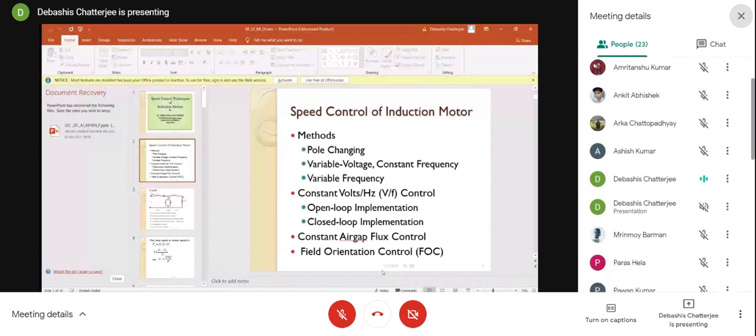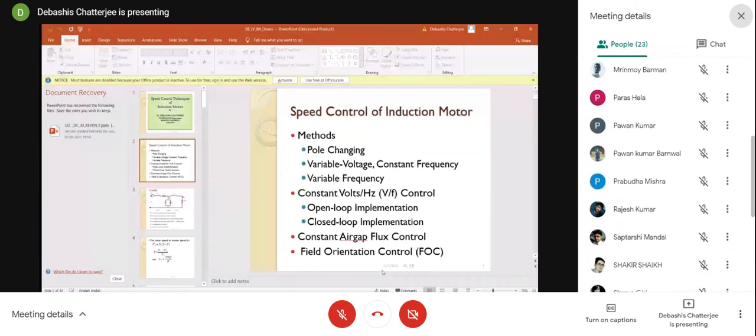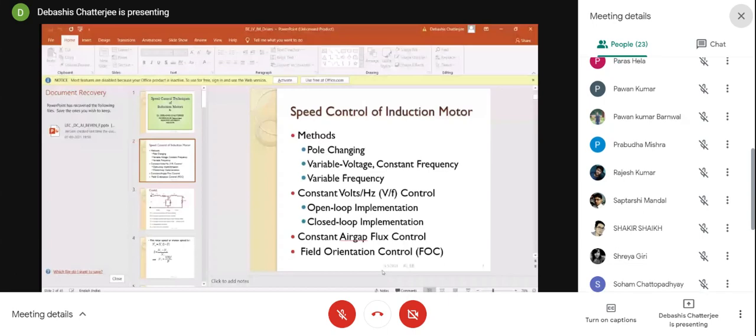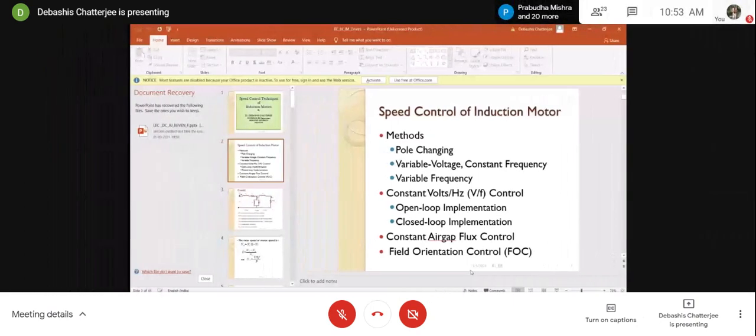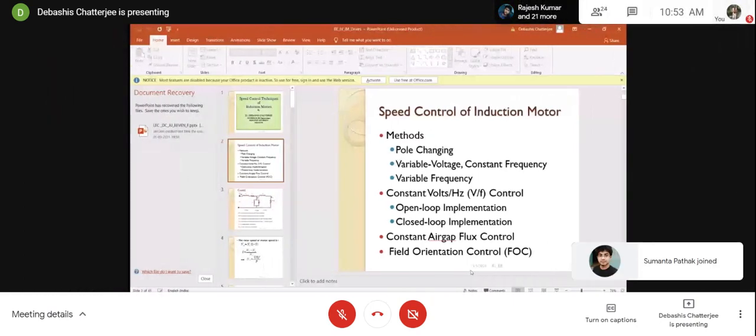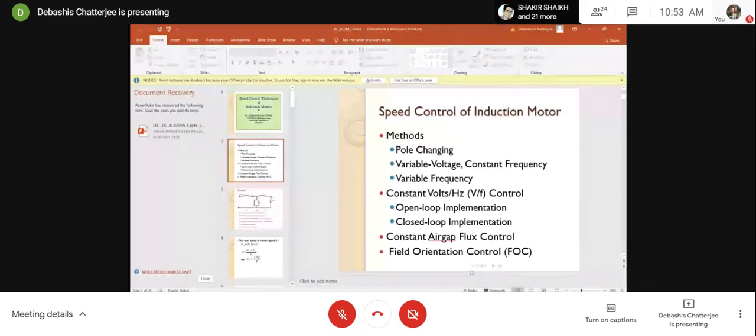Now the first question was: why is rotating flux produced, when you are giving a pulsating three-phase flux? That should be clarified. The rotating flux is created because we apply time displaced current to space displaced winding.